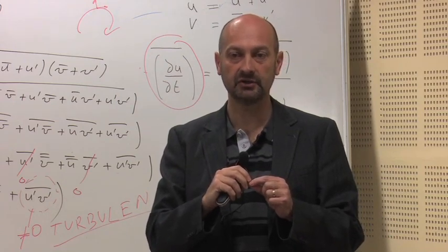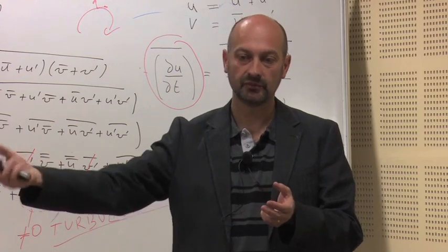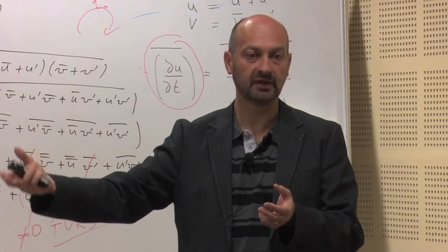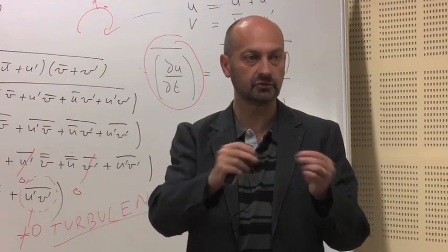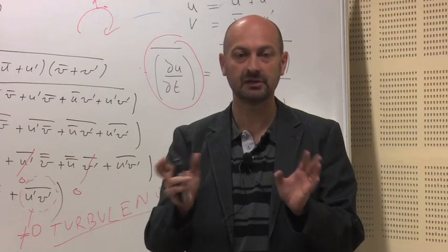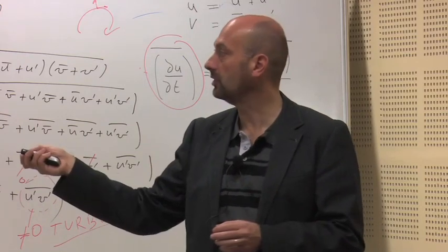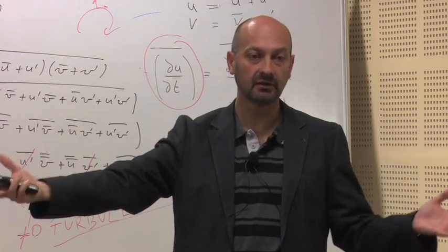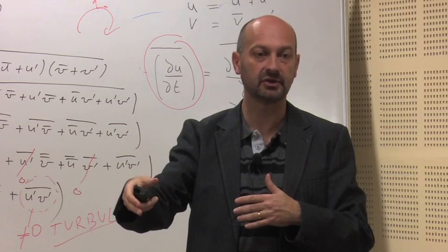Another way of validation is to use your CFD code, and then you have some benchmark. So you have some experimental data, and then you are going to validate your simulation against some data. But then you are facing problems because you are not going to simulate maybe the whole thing. You are going to assume that the inlet condition is something, maybe in reality it's not the same.